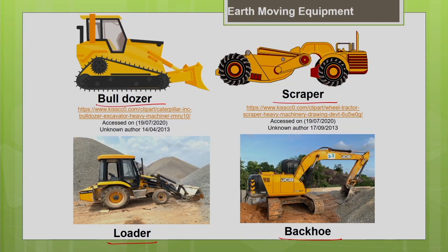So, basically for the earth moving operation, which equipment do I need to select? First, you need to think about the haul distance needed. What is the haul distance needed for your project? Because every equipment has its own economic haul distance.